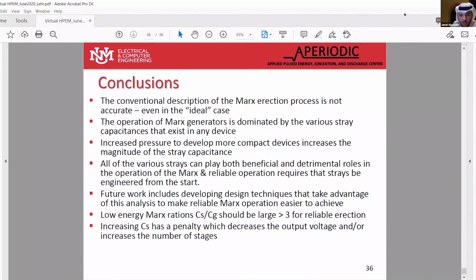When you design compact transportable pulsers, you end up increasing significantly the stray capacitance to ground. These stray capacitances may start to be comparable with the stage capacitances or the peaking capacitance and become an issue. What do you suggest to overcome this trade-off? Briefly, if you can.